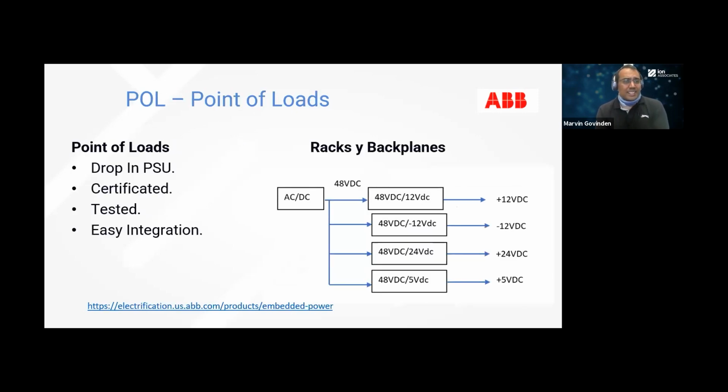So what does that mean? What do these bricks and these point of loads mean to us? Well, they're drop-in power supply units. They're certified, they're tested, they're easy to integrate. So if you have, say, 15 different cards in a rack which perform different functions, you can have maybe 2 boards there where you are supplying power to the whole rack in a redundant system. So you have an AC/DC coming in somewhere in your system, and you're getting 48 volts out to the rack, you could say.